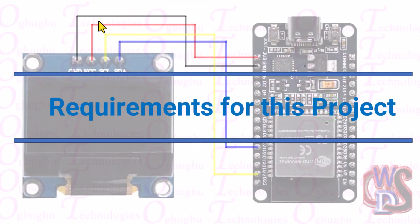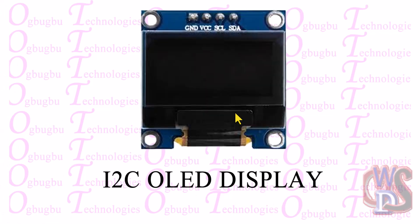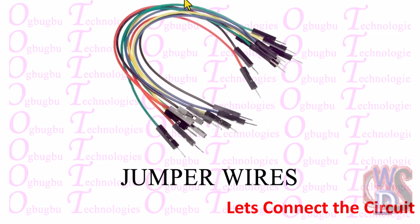So right now, the requirements for this project are an ESP32 board and an OLED display. This is an I2C OLED display. So you can see it has just 4 pins: ground, VCC, SCL, and SDA. We also needed a breadboard for the connection. And these are our jumper wires, which were used to join our components together. So right now, let's go into the circuit connection.